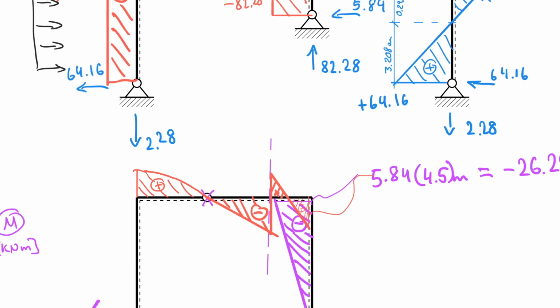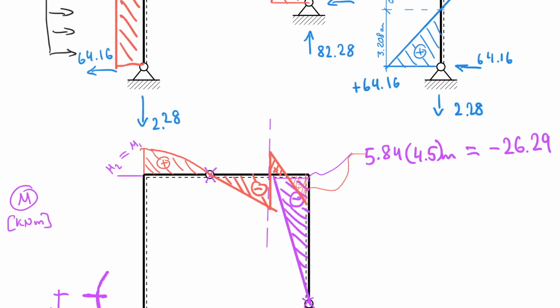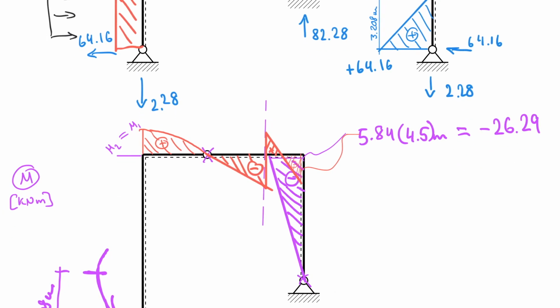And again, it's a 90-degree corner. Actually, it doesn't matter if it's 90 degree or not in this case when it's the moment, but of course the value here on both sides, M1 and M2, are equal to each other. And again, linear. I have to make a linear connection between those points, so let's do that. Technically, my drawing doesn't show it, but technically this tangent here actually is tangent to the curve at that point.